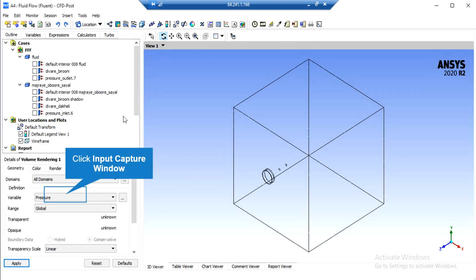In order to extract a 3D contour, you just have to click on the Volume Rendering button and accept the appeared window. After that, on the low left side of the software window, you can see that a new part will appear. In that part, in front of the Variable section, you can select your desired variable. For example, in this slide, we are going to select the liquid volume fraction. After defining the variable, by clicking on the Apply button, the software will show you the 3D contour.